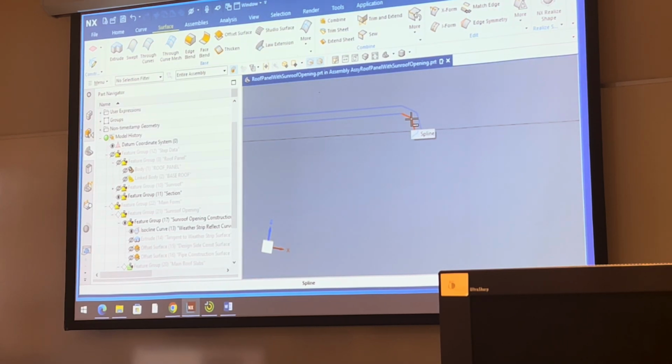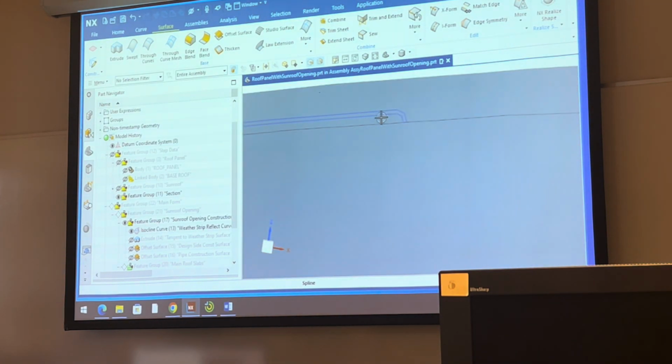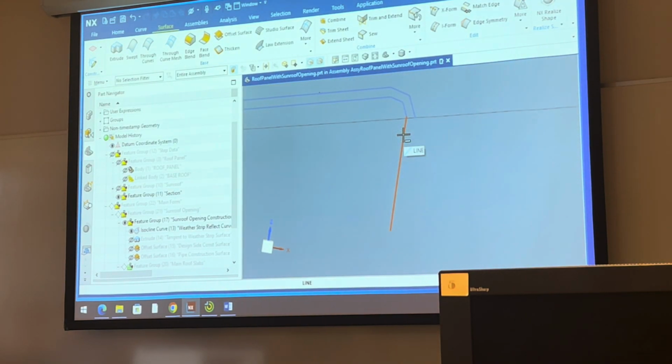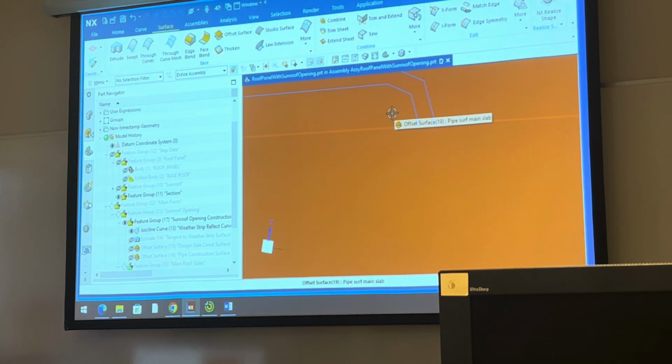And it's based on the bend radius. So the bend radius is 1.5. That's in here, inside the circle a little ways, about like so. So what we just did was we offset this guy down by 1.5. We're gonna offset this guy over, I think we already did that in the last exercise, 1.5. Where those two surfaces meet will be right here, where the middle of that bend will be.